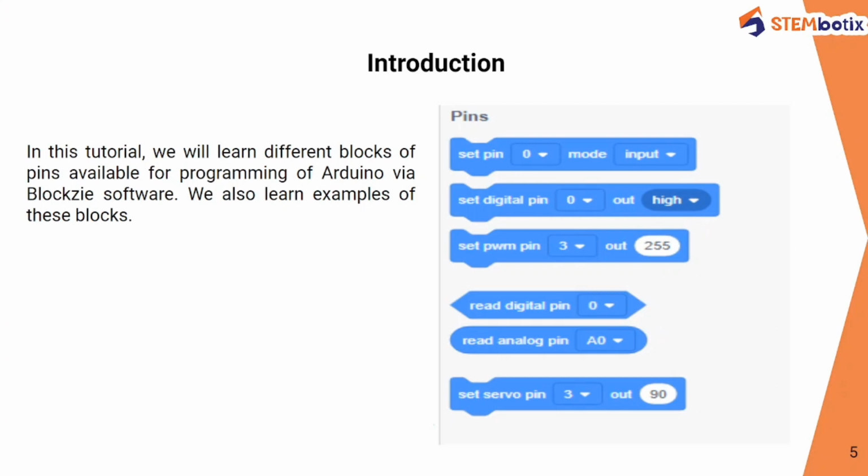Let's have one LED example. We can use this LED example usually in every programming. The LED is basically an output device for the Arduino microcontroller board. Let's assume that we connect our LED to digital pin 3. So here we will set our digital pin 3 as an output.